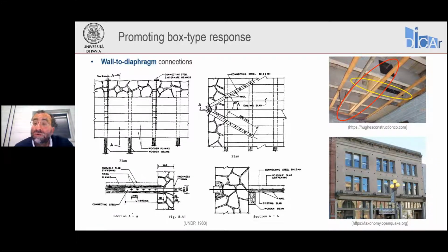In the orthogonal direction, within the red ellipse, we have instead a threaded rod, with a bearing plate against the perpendicular joist, and then you see that parallel to that rod, a blocking system has been introduced so as to resist the compressive force and avoid bending the joist where we have placed the bearing plate.